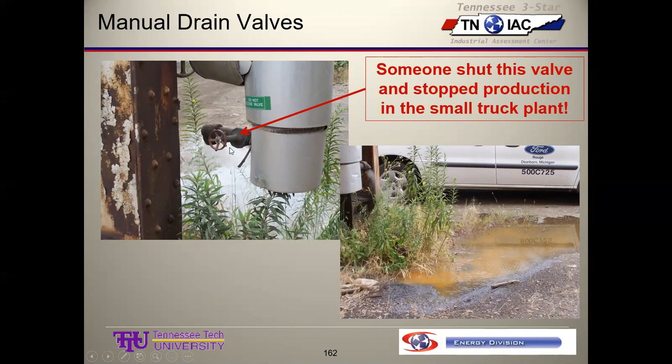We couldn't believe it. We wrote up a recommendation for $2 million worth of desiccant dryers to put in their compressed air plant. Did they do it? I doubt it. But not only that, you've got water, you've got corrosion. Those pipes are going to corrode from the inside like crazy. You got rust, all that compressed air blowing by there going to pull those particulates out. And anything that air goes to that can get clogged or plugged up, it's just a maintenance nightmare.